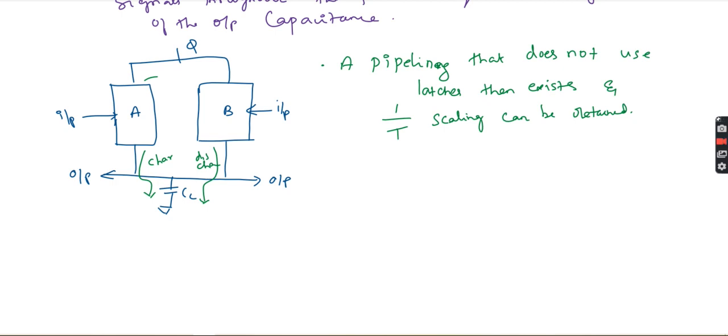But this method will not give the solution because the resources are limited. The ability to drive the control signal for the de-energizing path is guaranteed if all the logic blocks, whatever the small logic blocks will be there, are implemented as invertible so that their inputs may be recomputed from the output.